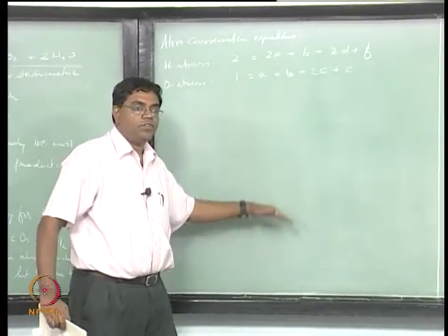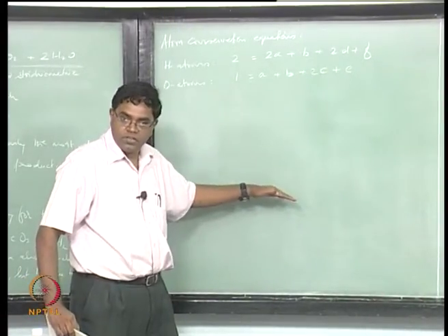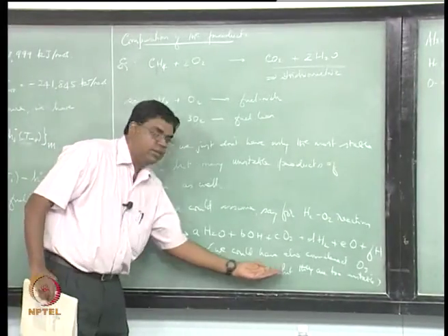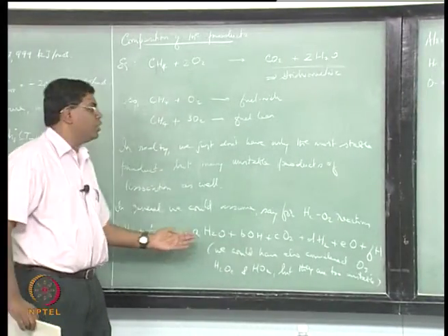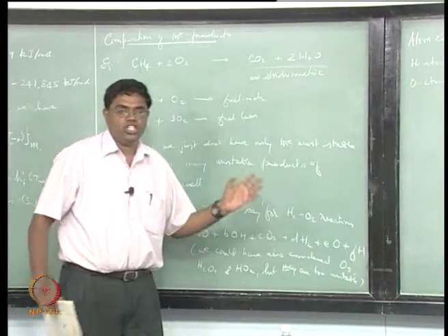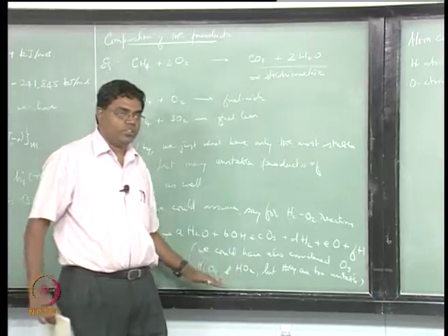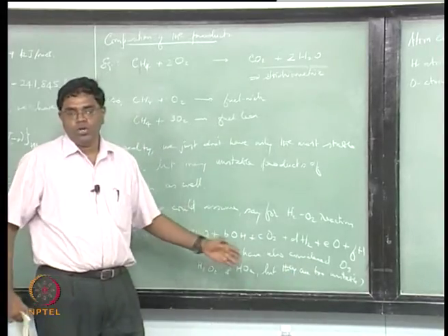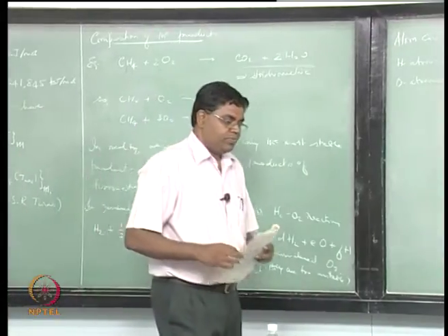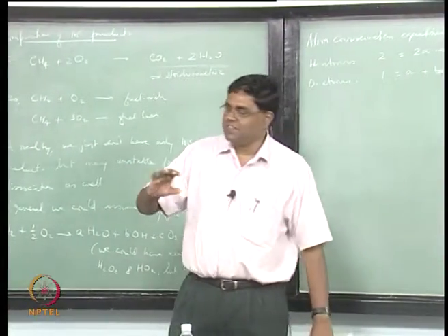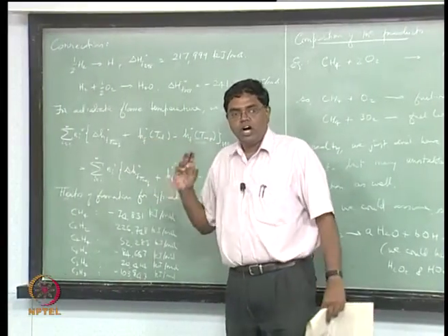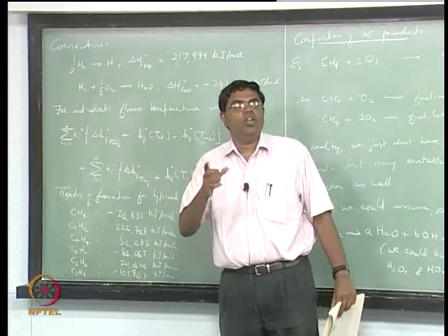That means we now have to develop 7 more equations, and what we expect to find is these will be in very trace quantities. That means if you now had after H, if you had G, H and I, these G, H and I values will be very small, is what we are expecting. Therefore we are neglecting this. So the final answer for the adiabatic flame temperature actually depends on how many products you are willing to consider.